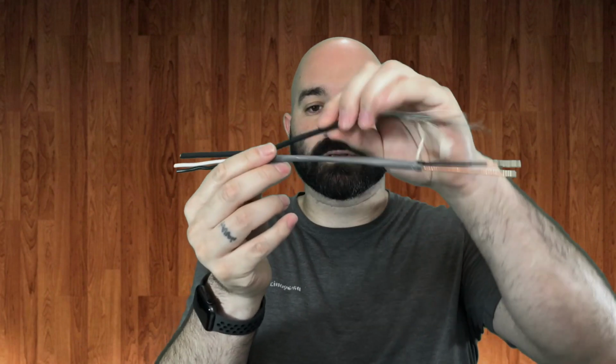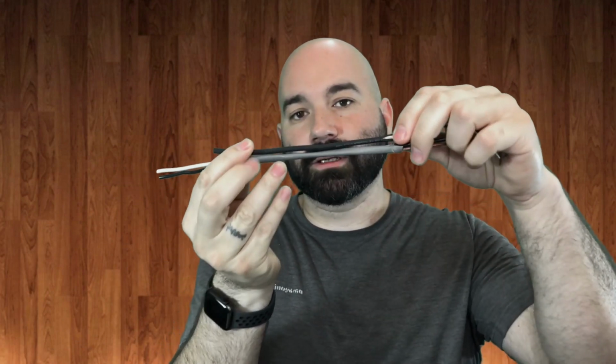And the second example, let's say on your computer desk or on the stage or something like that, we have different things plugged into different sources. You're going to have power cables run into audio cables at some point. It's not 100% unavoidable. But what you can do is reduce the amount of layover between the two cables. The more surface area that you have between the two cables, the more EMI that's going to be introduced into your cable.